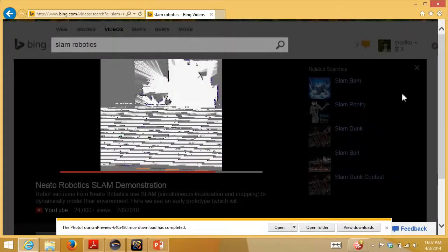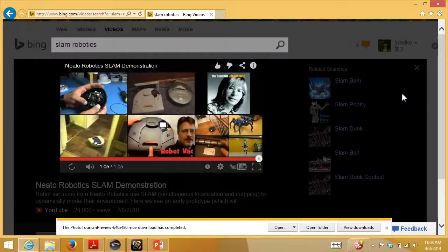The other thing about SLAM that's a little bit different is that the robot probably has some sort of odometry on it, so it has some sense of how far it's moved, because it maybe can track how many times the wheels have rotated. And so there may be some side information about 3D position that you can use to help in your estimation problem. Even if the robot's wheels are not super accurate, you may still get a nice initial position for the robot that you wouldn't have in the camera tracking problem.